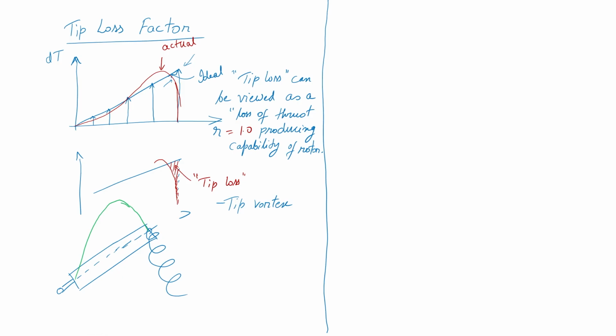So, this is my thrust distribution, and because it has to come down to 0, and of course, the way we have tip vortex in fixed wing, same way we have tip vortex in rotary wing, which is because of the difference between your top and bottom pressures. Okay. So, that you will remember, right, that the pressure over the top surface of the airfoil and the bottom surface of the airfoil is not equal, and therefore, the flow would go from high pressure to low pressure. Okay. So, which creates this vertical kind of thing which results in tip vortex.